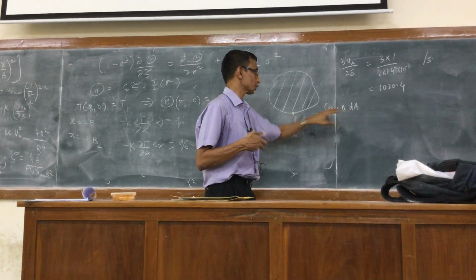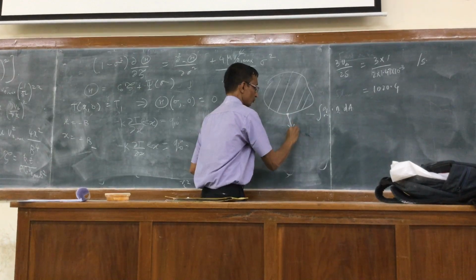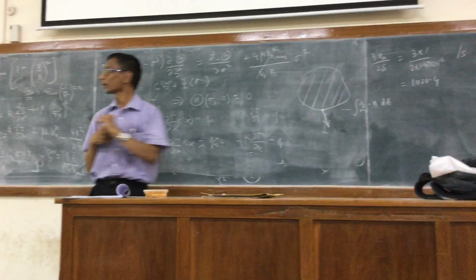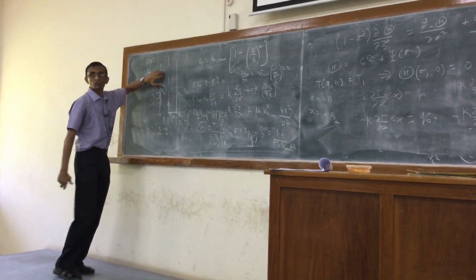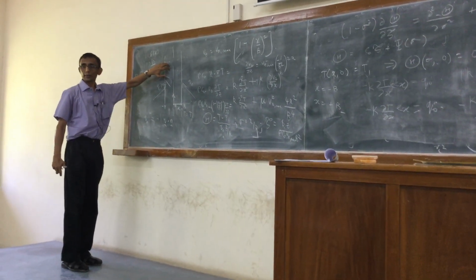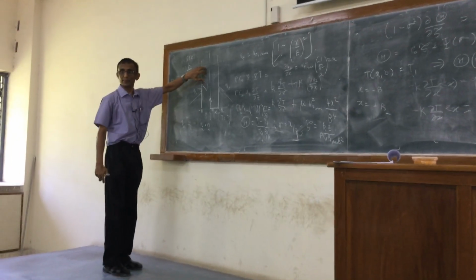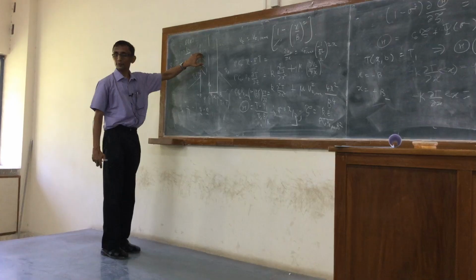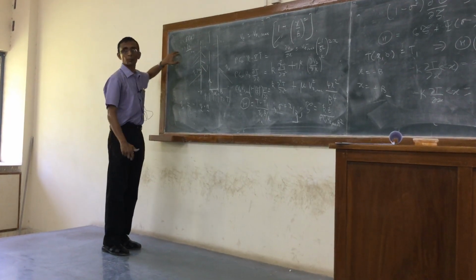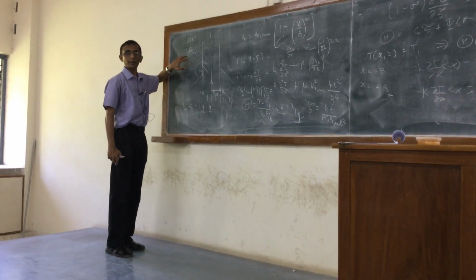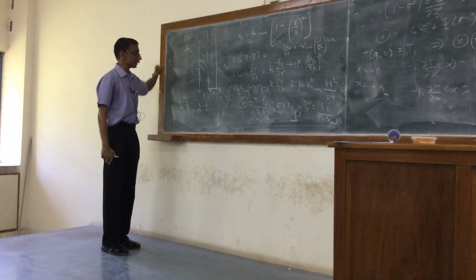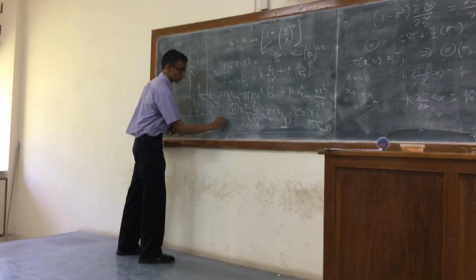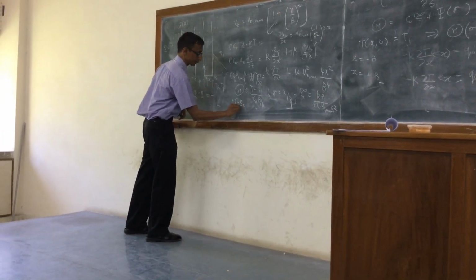So I am having minus q dot n. The n is from the body outward. Here the fluid is inside. The body which is receiving the heat is the fluid, right next to the wall. So the outward normal would clearly be minus e_x. So I have minus of q, dotted with minus e_x.